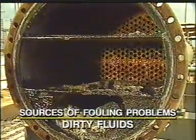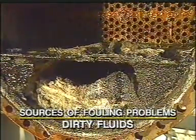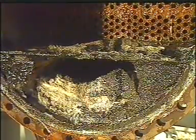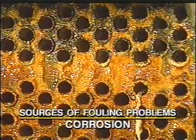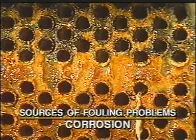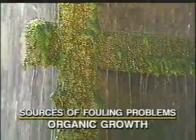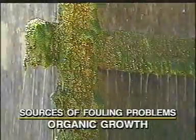The deposits have several sources. Process fluids may contain solid sediments. Once they settle, a restriction to the flow develops, and the restriction then causes more settling. Corrosion is produced when the metal of the exchanger interacts chemically with the process stream. These deposits can break free eventually and foul the exchanger tubes. The warm exchanger provides a comfortable environment for the growth of certain organisms. The tube surfaces may become contaminated with algae.